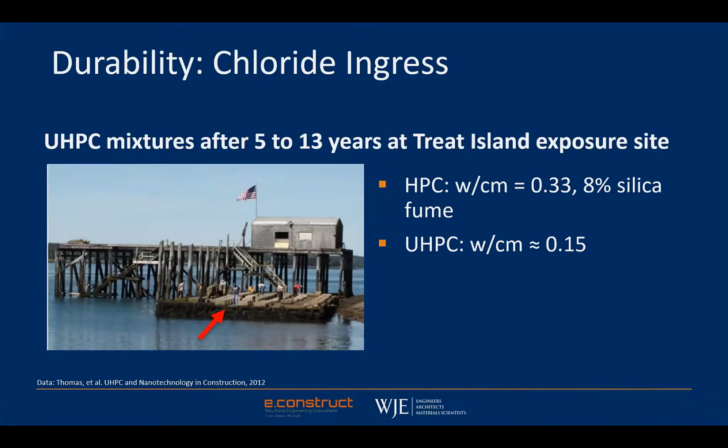This is an area where there's extreme exposure to marine environment. The tides there are as high as 6 meters, and they get as many as 100 freeze-thaw cycles a year. So there are a number of samples that were put out onto the site for up to 13 years and exposed to those conditions. The red arrow that I'm showing in the picture there points to some of the samples that have been put out there.